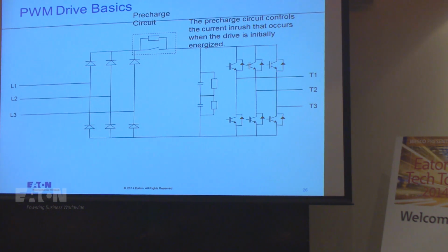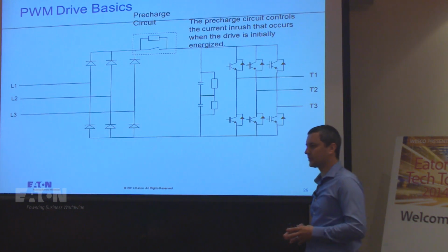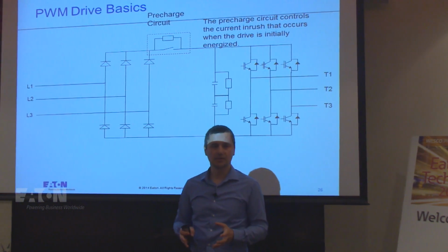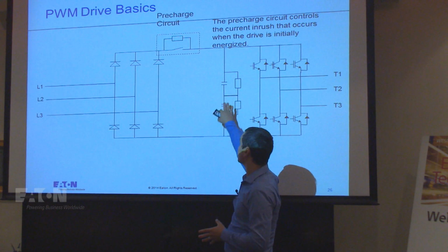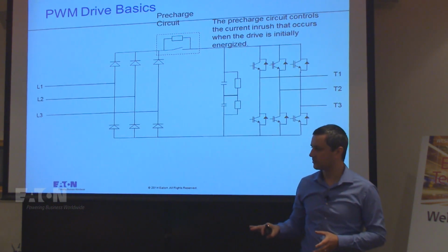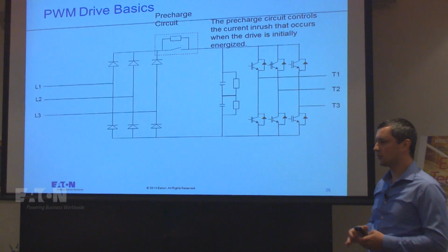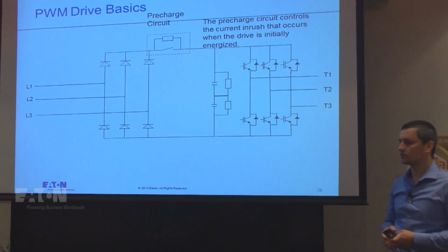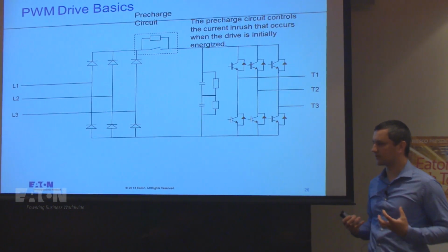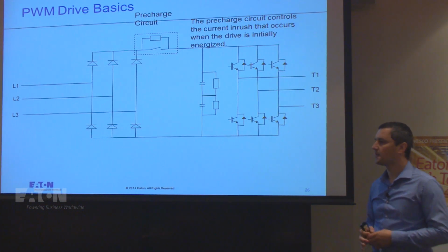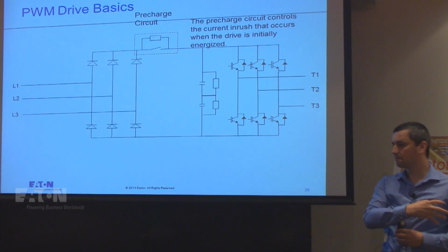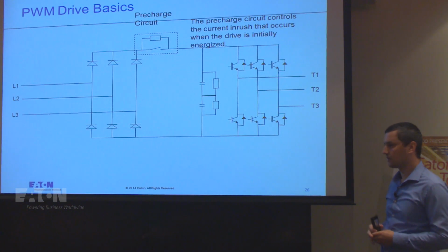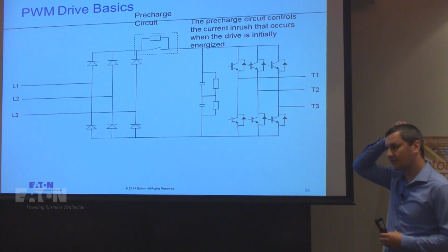Okay. Precharge circuit, this is standard with most of the drives. Why do we have a precharge circuit? On the DC bus we have capacitors, okay, which are here, and we will touch a little bit later on them. Capacitors, usually when you're starting the drive, they want to do what? To suck a lot of current, okay? They're very, very hungry. If you let that happen, you'll have a big inrush current, which can damage your rectifier.